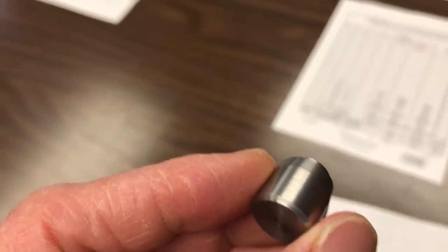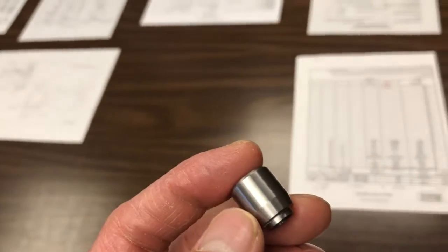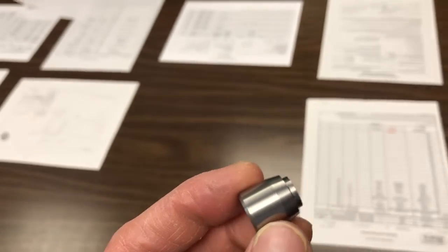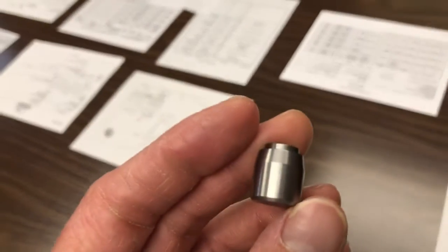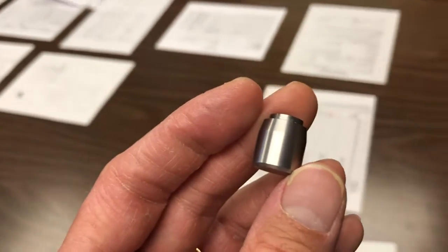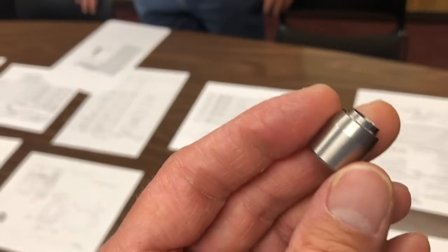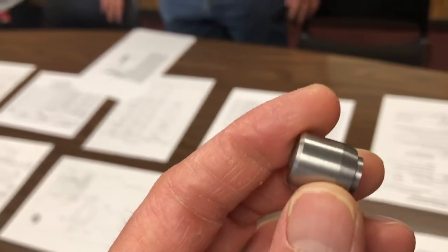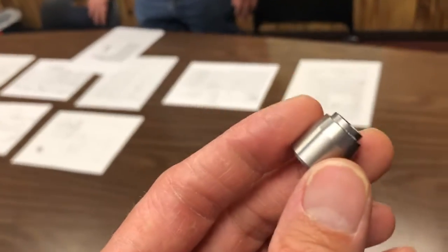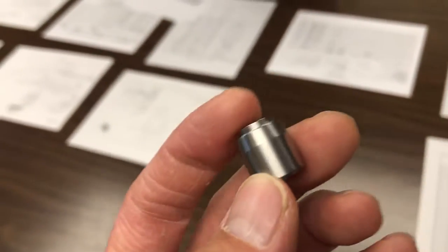I know it's critical. We actually made an update to the process for production. Through all of the analysis, we decided to grind the OD. That's correct, because it's a press fit. This check valve goes into another part, I think it's called a sleeve. Yes. And there's about 1,400 PSI that we found out through discussions with our customer, because they were very, very cautious in how they check the outside diameter, where we have relatively little tolerance compared to the inside. That's correct. There is very little tolerance on that.